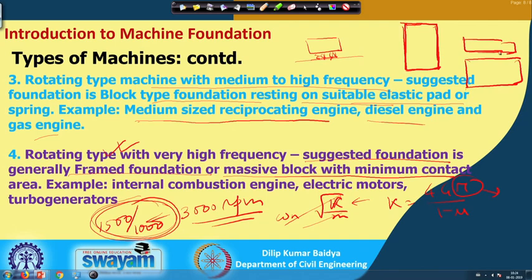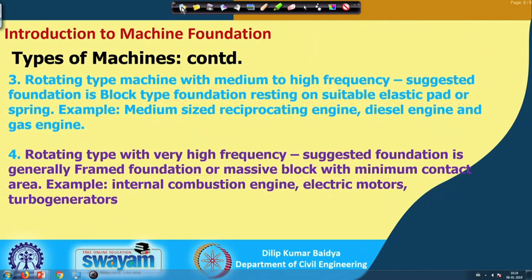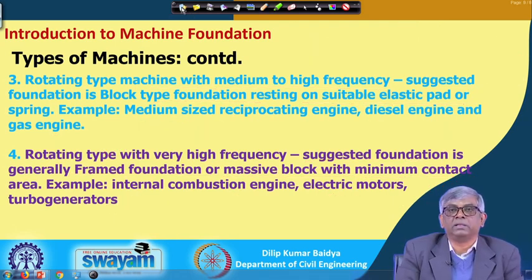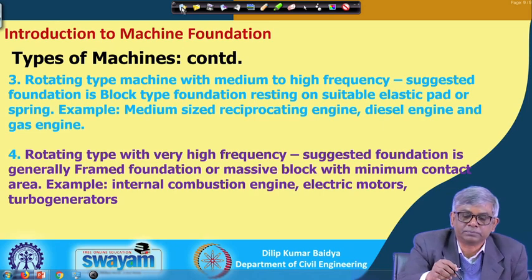Okay. So, these are the different guidelines. If you know the type of machine, then you can adopt accordingly, whether it is a block with small contact area, block with large contact area, or frame foundation, or you can have the block foundation with some absorber. So, based on frequency range, we can decide that.